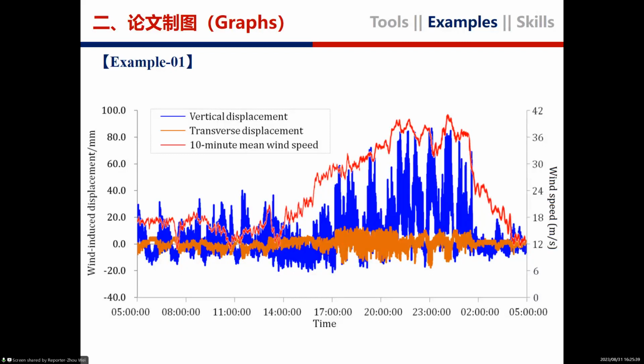In MATLAB or Excel, we can use legend to describe the explanation for each line. Here, we have something to declare. If the time history curve of transverse displacement is below vertical displacement here, readers or reviewers cannot see it. From this perspective, we need to plot the data curve that has the largest magnitude at first, the second largest data curve in the second order. The final plot of data curve must be the curve with the smallest magnitude. Only in this way, details of all data curves will not be covered by each other, okay?